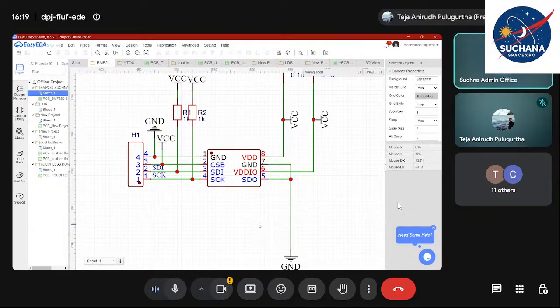So to resolve this issue we have something called muxes. Mux means multiplexer. There are two different things, one is a multiplexer and another is a demultiplexer. With the help of multiplexers you can solve the issue. You can operate multiple modules even though they have the same I2C addresses.